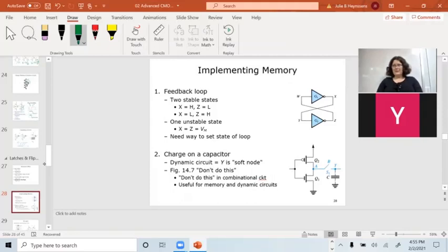Then the next thing is, okay, we want standard cells. We want AND gates and OR gates and all that good stuff, and flip-flops. Normally you would go to an IP vendor, somebody who does the IP for that process, and just buy them. We could not get anyone to agree to sell us their IP once they had heard this. This was too weird. So we started from scratch. We built our own AND gates, our own OR gates, our own flip-flops. Building our own flip-flops was a job for Bruce Hancock, and I'll explain that when we get to setup time.